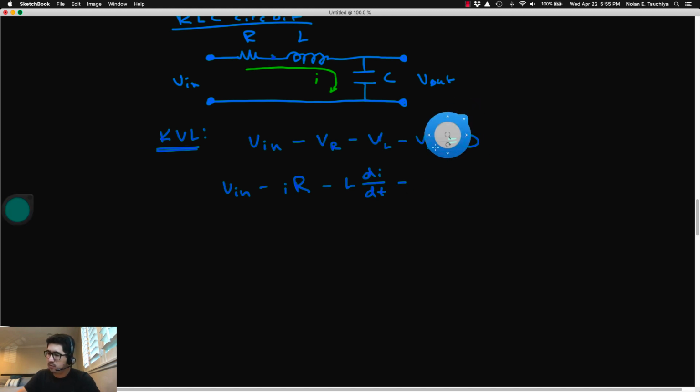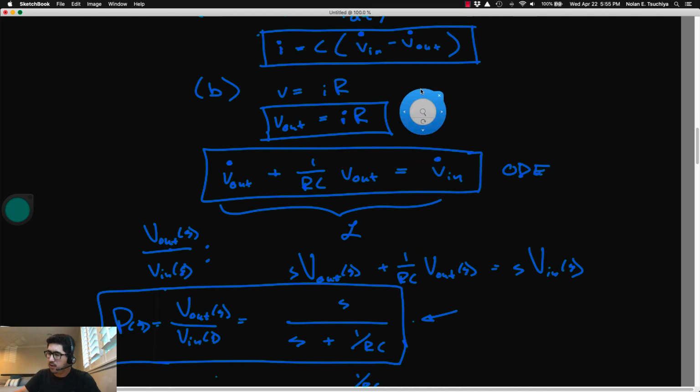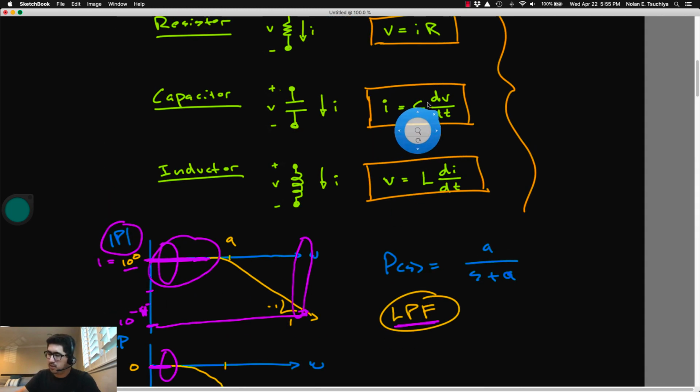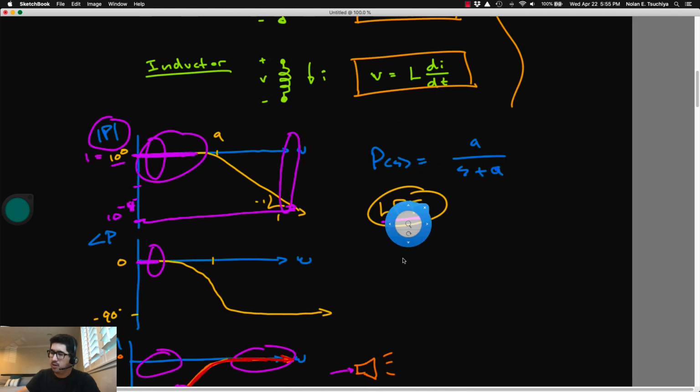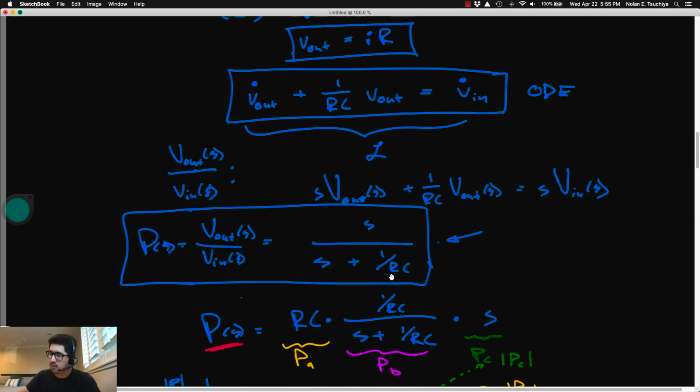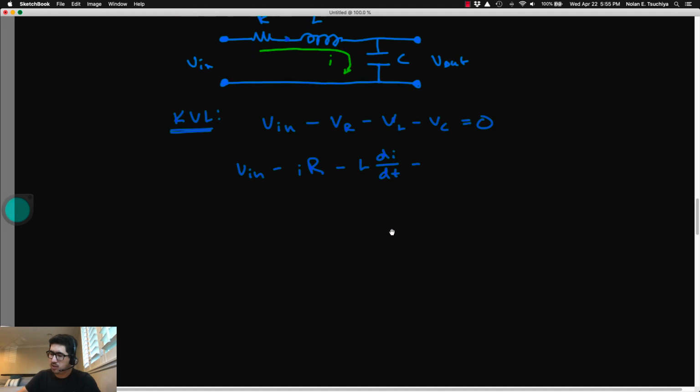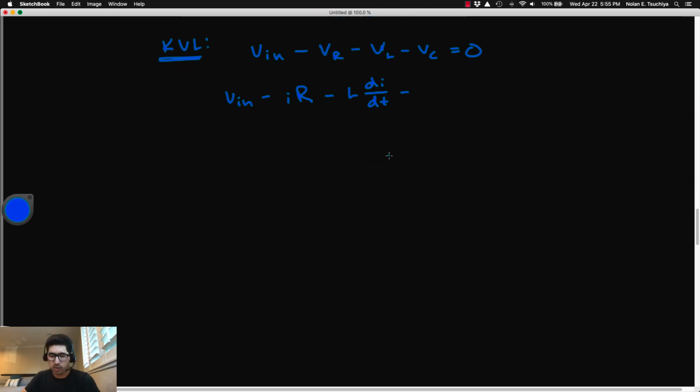Now the interesting thing is for the capacitor. Well, we've been given the expression in terms of the current for the capacitor. Okay, so for the capacitor, the law is I is equal to C times dV dt. If we wanted to solve using the capacitance law for the voltage, we would have to actually integrate both sides of this to solve for the voltage across a capacitor. Okay, so we can actually do that, and it seems like it may get pretty complicated, but we're just going to apply it and then we'll handle it a little bit later.